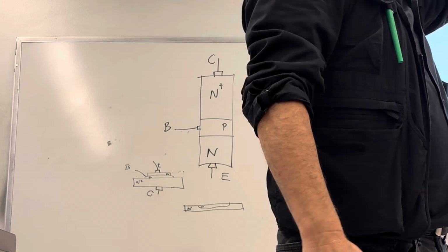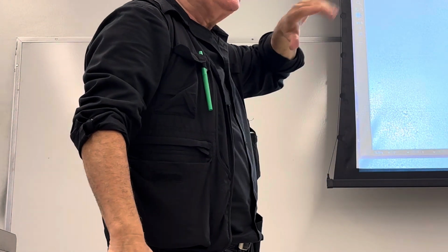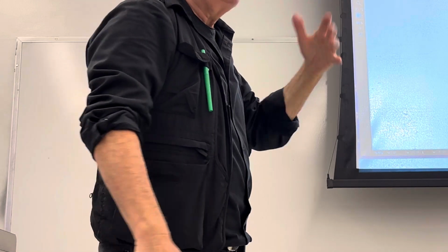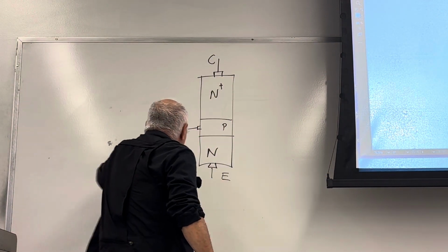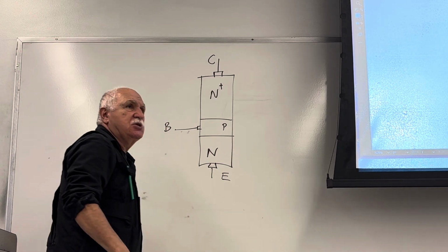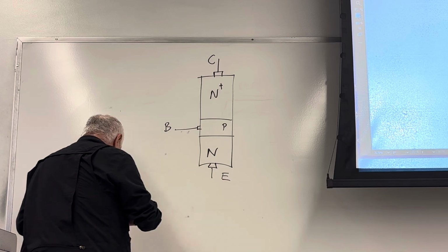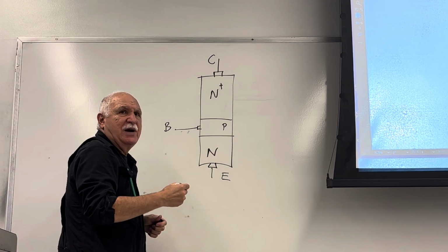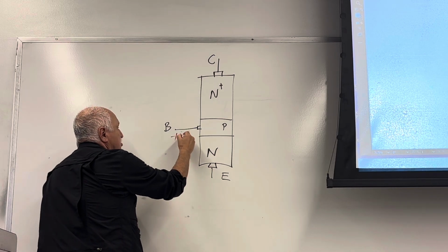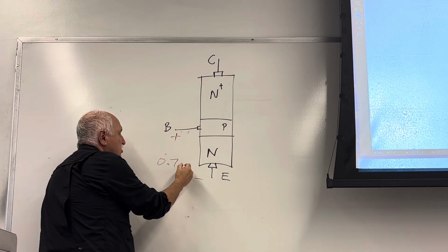If you put it in the right direction, collector and emitter in the correct position, then you will get high beta. Okay, so having said that, let's see which one is the forward junction. Do you recall the 0.7 volt we had at the time of biasing? Positive 0.7 volt. This is the forward.